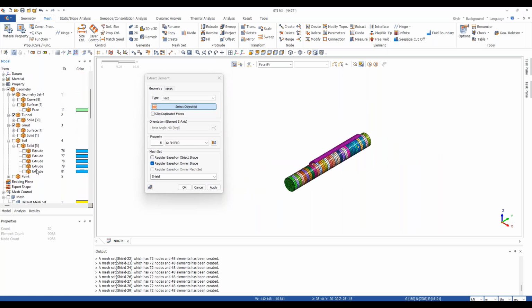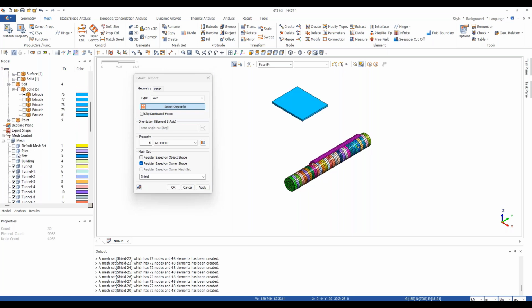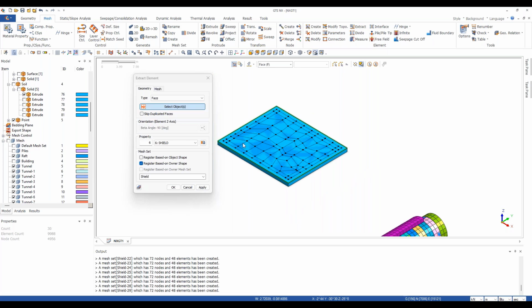Now the next part is to mesh the ground surface. Okay, now I'll choose the first, then I'll also need to activate the raft and the points as well. Since I need to include the points, I have imprinted them and I need to include them. I have created the points. I need to imprint them onto the meshes, so that your raft is considered in the analysis.